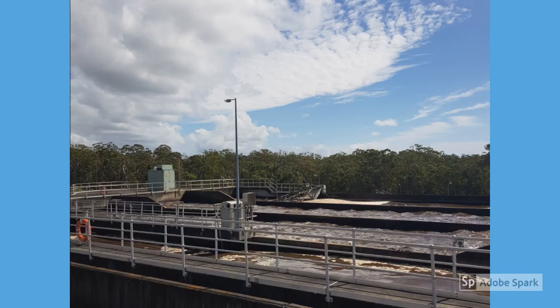From here, the wastewater enters the main section of the biological treatment tank with a volume of 9.9 megaliters. The brownish solution filling this tank is called activated sludge and is a flocculent culture of bacteria developed in this tank under very specific conditions. This tank possesses aerators and an oxidation ditch for the growth of aerobic bacteria.